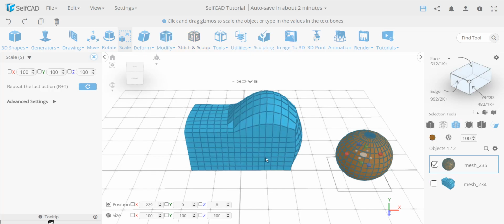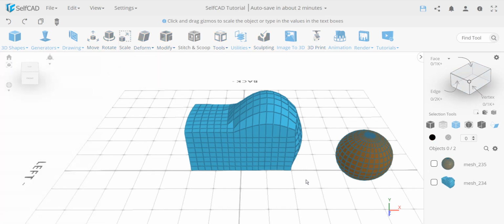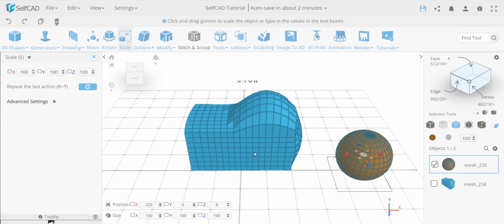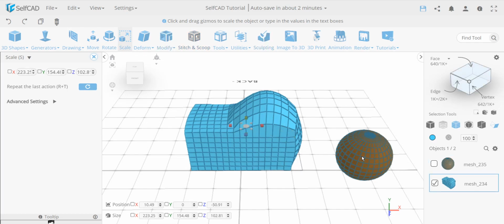And what I do now here is actually an interesting trick. In most tools in SelfCAD that have a check mark, where you need to confirm something, you'll be limited to what you have entered. It's a selection-first application, meaning you select something first and then you enter and do it. But in some tools like these, you can make changes in the middle. If you deselect everything, the tool will close. So if you want to keep repeating transformations like I did before, you can just select one object, enter the tool, then select the next one and click again on the first one to deselect it. That's how you can keep on playing without really closing the tool.